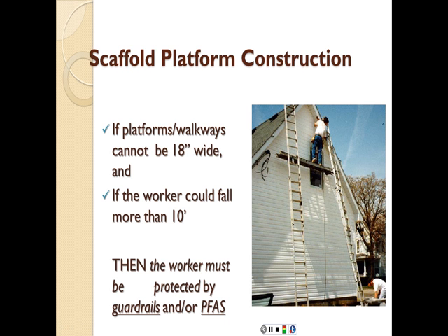Now here we have... how would you classify this? Would this be a platform scaffold? It's definitely not a suspended scaffold. Here we have several violations, by the way. No fall protection whatsoever, very narrow scaffold not properly erected, no hard hat. So again, several violations in this picture on its own.